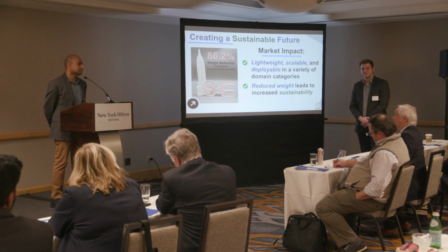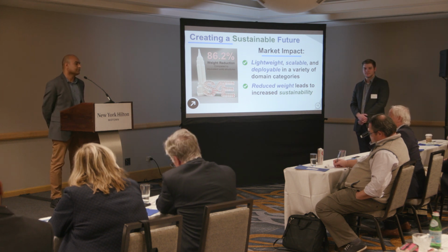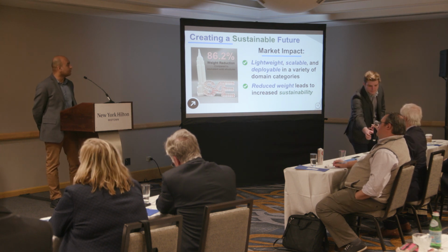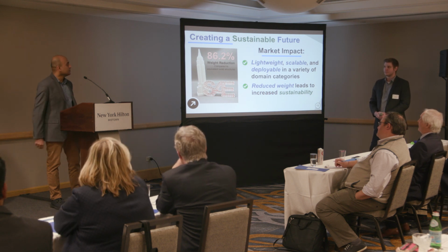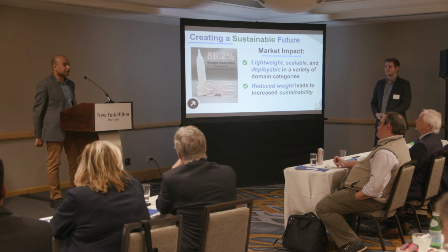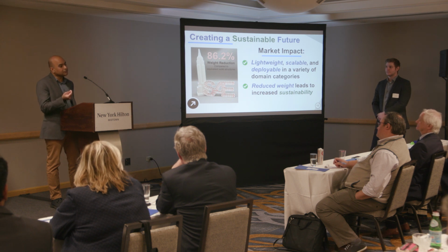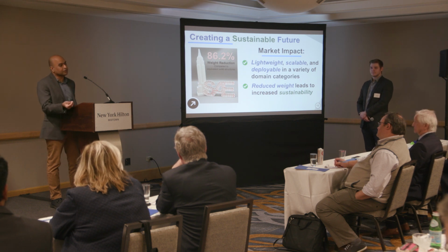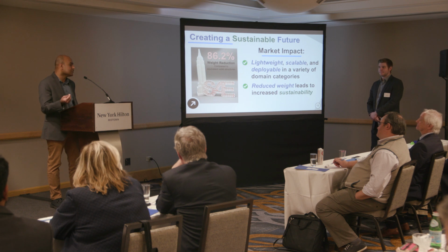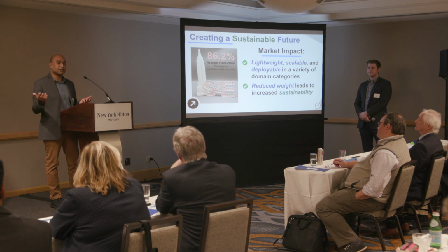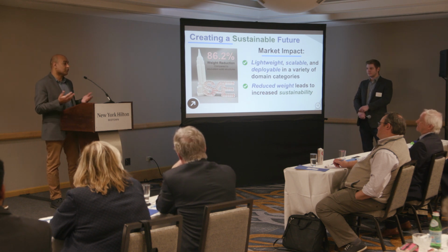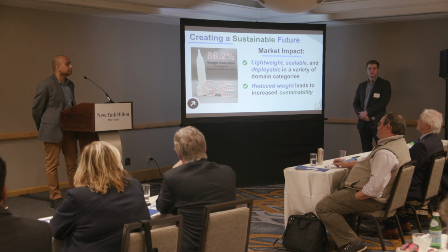Do you have a resolution limit for the printing process? No. So it all depends on the 3D printing method that we are using, which is basically an extrusion-based method. So we can go very, very high resolution. That depends on the material that you're using, right? The capillary effects as you're extruding from the nozzle might affect things, but that is different for every single material. And on the larger scale, with extrusion-based 3D printing, people are also printing houses. So we can also print very, very large structures as well.